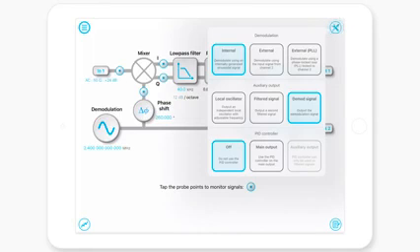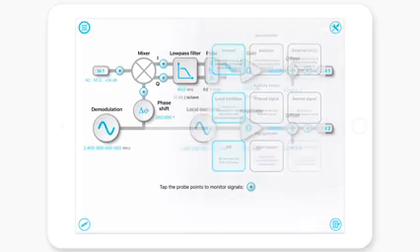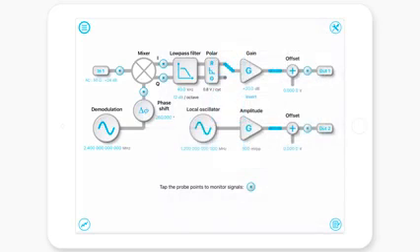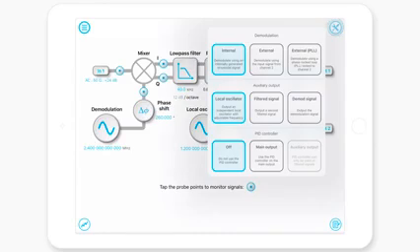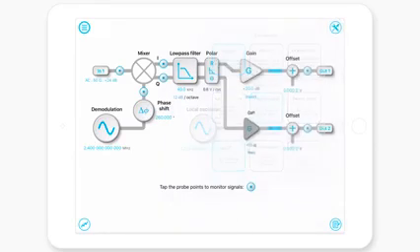You can also configure the path of the auxiliary output. By generating a standalone local oscillator, you can demodulate with an arbitrary frequency, such as a higher harmonic. Or select the filtered signal option to send both demodulated signals to the analog outputs.